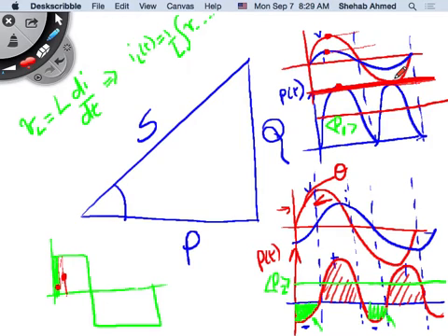When I put AC now, what happened? I've lost some areas. These areas are basically an indication of the amount of power being transferred. I have these areas here that don't have voltage multiplied by current. So these are areas where I'm not able to transfer instantaneous power, which means that my average power has been reduced, right? And that's why people now are talking about high voltage DC.